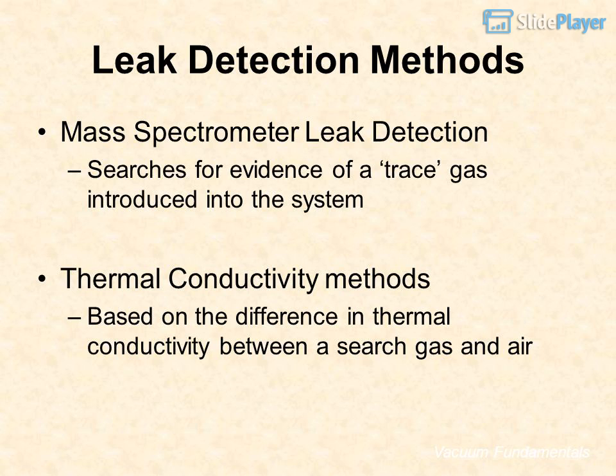Leak detection methods. Mass spectrometer leak detection searches for evidence of a trace gas introduced into the system. Thermal conductivity methods are based on the difference in thermal conductivity between a search gas and air.